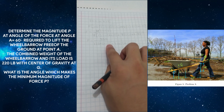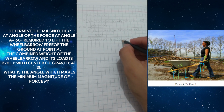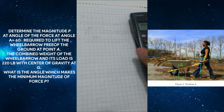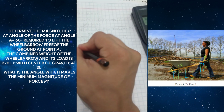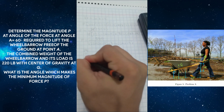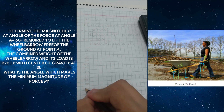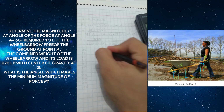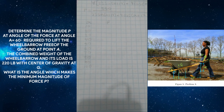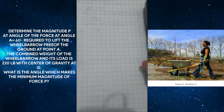Well, to find the angle which makes a minimum value for P, I'm going to make a table in which I'm going to give the angle of alpha different magnitudes, and then I'm going to calculate the value of P. Here we have 10 different values for the angle alpha, and I'm going to put this expression into the calculator.